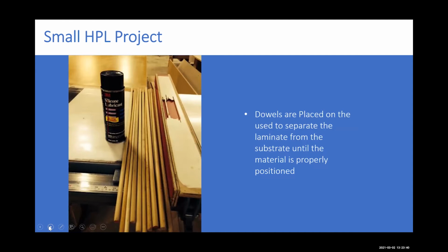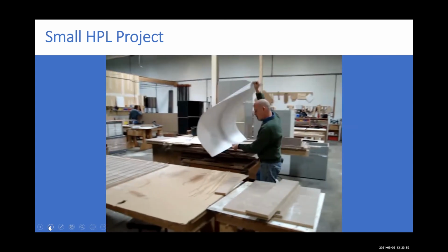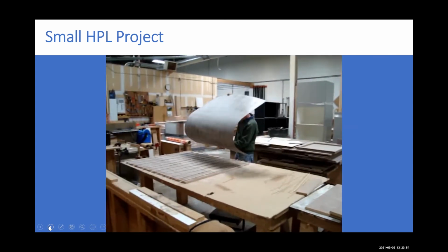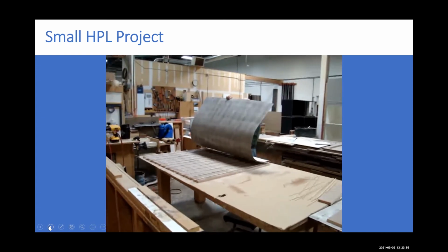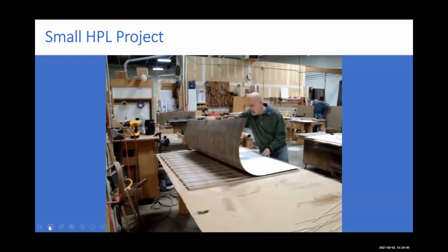Dowels are placed on the substrate during open time. They are used to separate the laminate from the substrate until the material is properly positioned. So here he's going to place the sheet of laminate over top of the dowels. He's got his substrate ready to go under there.